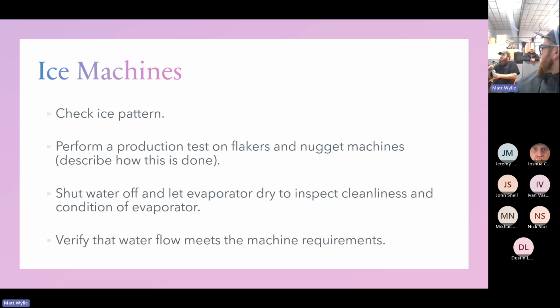Compression fittings, like the little quick connect. Yep. So keep in mind too, when Matt says 3/8 and 1/2 inch, he's referring to plumbing sizes, not refrigerant sizes. In refrigerant, we're always talking about outside diameter. So when I say 3/8 pipe on this filter dryer, the outside of the pipe is 3/8, which means the inside of the pipe is going to be even smaller. If you're a plumber and you say 3/8, you're going off the inside diameter. So you need a 1/2 inch inside diameter.